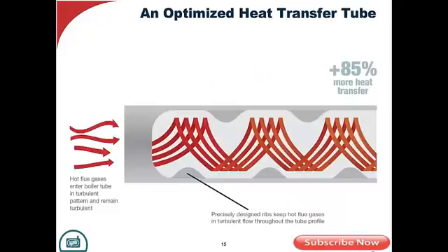Now, one of the things that boiler manufacturers and designers are doing today to improve the overall convective heat transfer in the boiler, to enhance that thermal heat transfer, increase the overall thermal efficiency, is to add extended surfaces inside of those tubes to break up the gas, to get away from the laminar flow, which increases the Reynolds numbers, which is nothing more than a ratio between inertial and viscous forces, and also the heat transfer coefficient, which is the heat flux ratio against delta T.